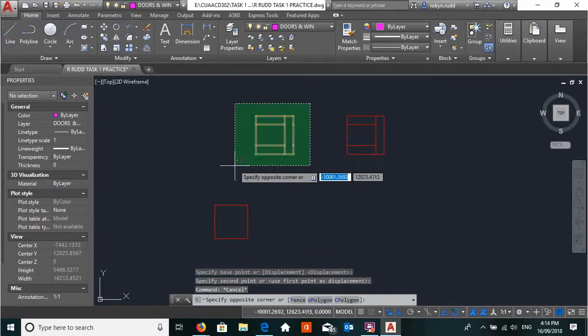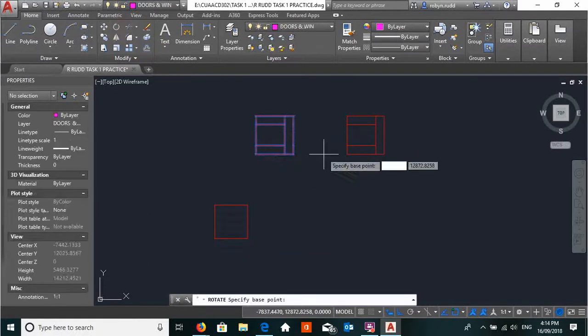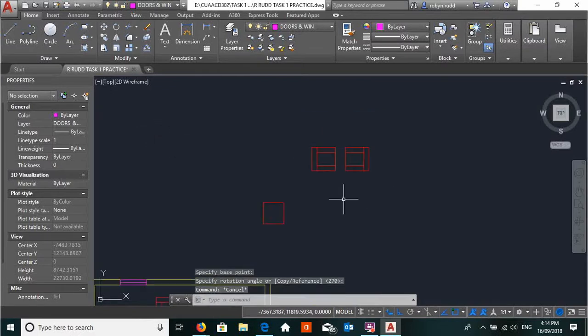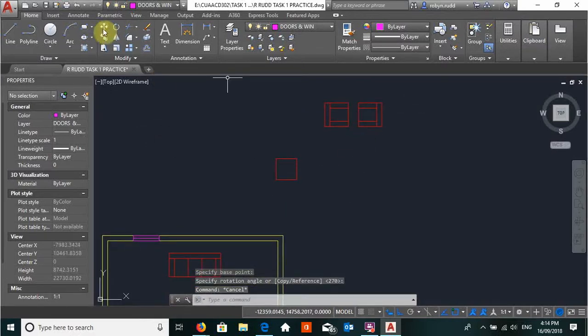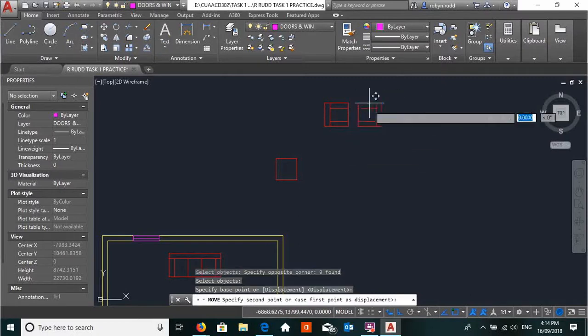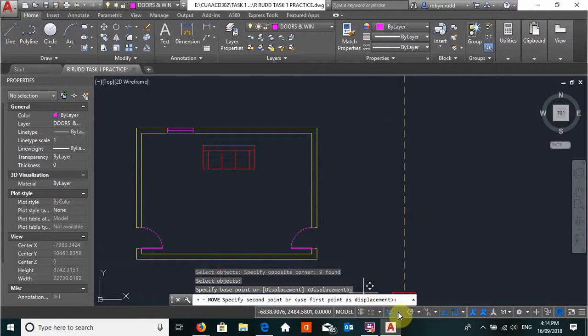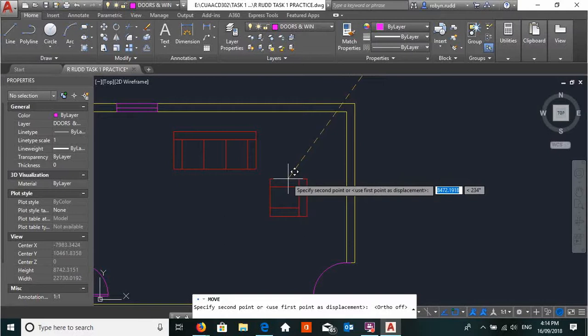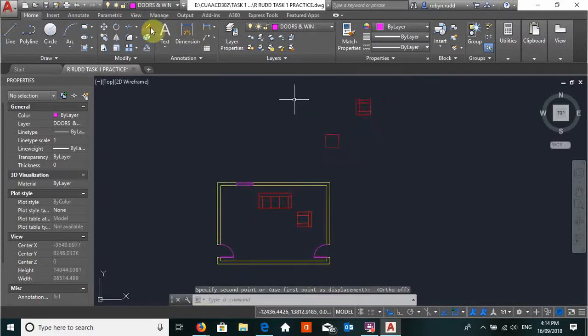and I'm going to rotate that now. Rotate, and there we go. So you just have to play around by pulling it. So I've pulled it 180 degrees, and now it's flipped it around to face each other. I now can move that one first, enter, in the middle there, switch off my ortho mode because then I can actually move it in the correct position, put it there somewhere, and I'm going to move this object highlighted by using the selection box.